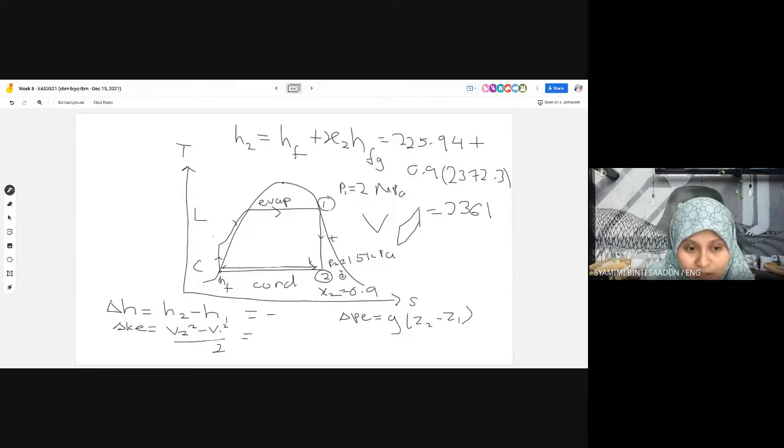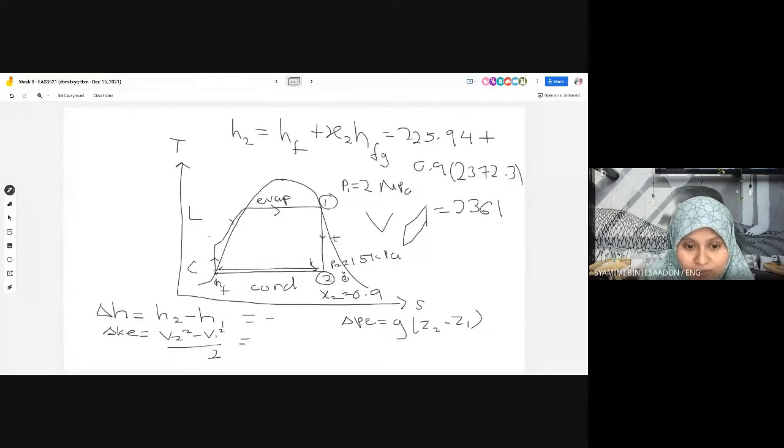Compression process kalau biasa ni, the liquid phase, starting from around the saturated liquid line. But here we have air, so we cannot use that one. It's not the same process. Table A6 is superheated water, kan. So if you took table A6, the process in the compressor should be liquid, but table A6 mentions superheated water, which should be vapor.